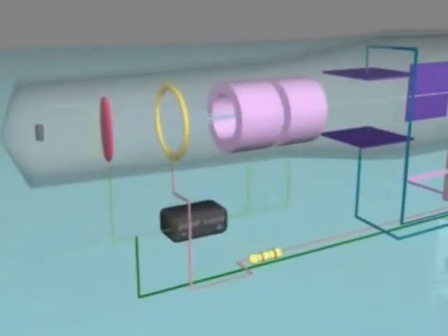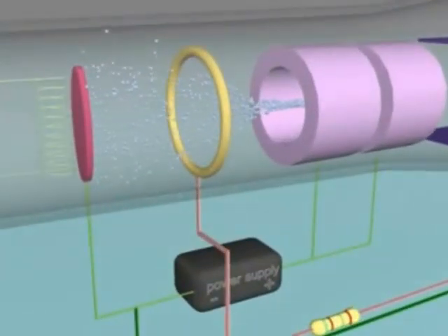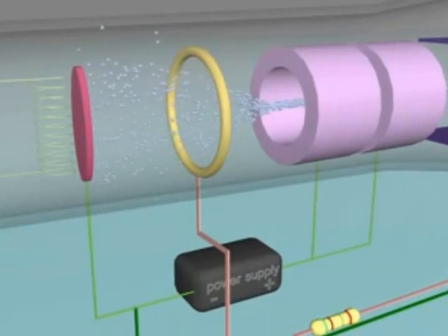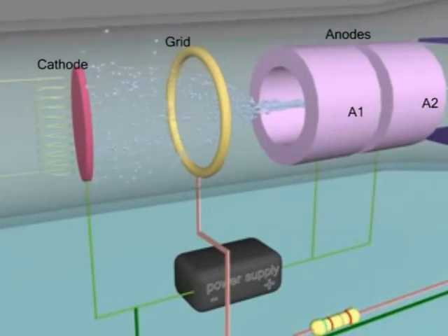The electron gun. The purpose of the gun is to supply electrons, accelerate them towards the screen and focus the beam to a point on the screen. It consists of a heated cathode, a grid to control the rate of electron flow, and anodes to accelerate and focus the electron beam. Each of the parts is maintained at a DC potential from an EHT source and a potential divider.